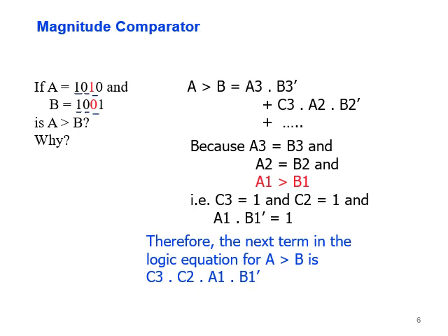What should I improve to make sure that it's correct? I do it like this. I start, as I mentioned, from the left, A3, B3 dash, to check this option for A greater than B. Plus A2, B2 dash, but I will multiply by C3, which is the output of the first expression here. And I go on, as an example here, it will be C3, C2, A1, B1 dash, and so on.